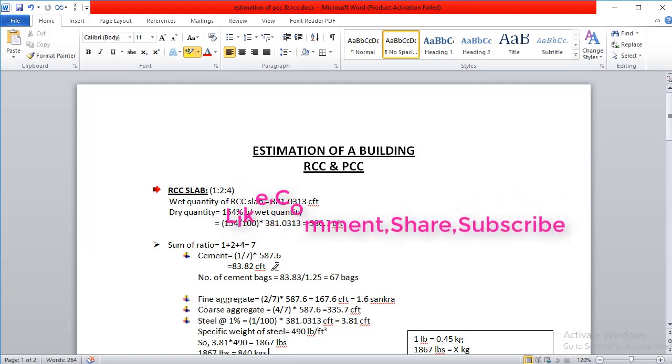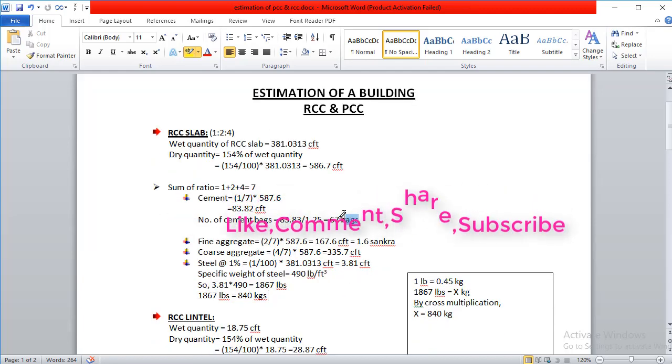Now to find the number of cement bags used in this particular RCC slab, we know the volume of one cement bag is 1.25 cubic feet. So divide this quantity of cement by the volume of one cement bag, and you will get the number of cement bags, which is 67 bags.